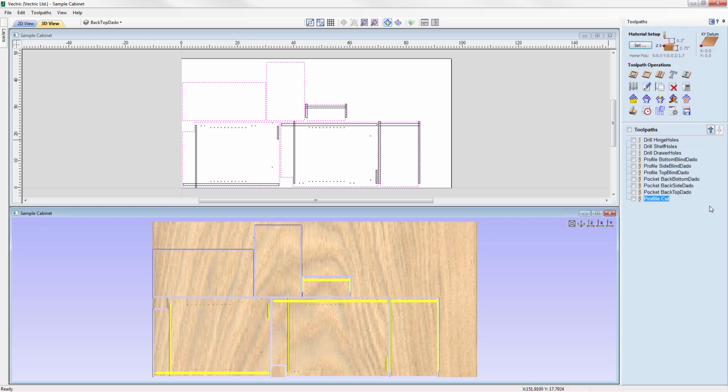Okay, so what we could do is go ahead and just save out all of the toolpaths to run them on the machine. The whole purpose of creating our toolpaths using this method of association with specific vectors and layers was to make use of the toolpath template feature. Now this layout is handy if we wanted to cut multiples of this design, where we could use the nesting feature to nest all the parts onto numerous sheets.